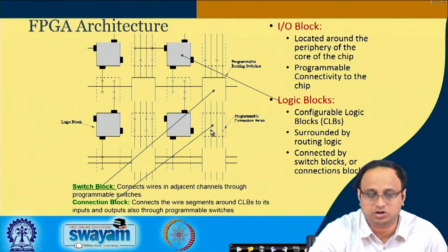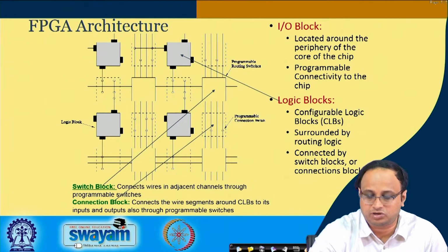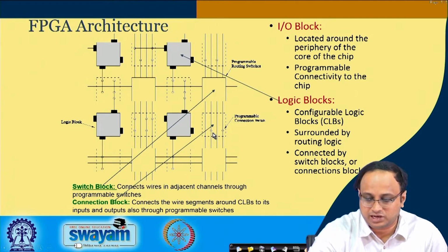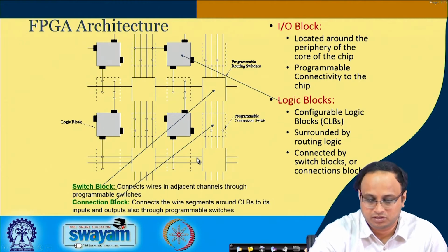For example, if I want to turn on a switch, I need to program 1 over there. If I want to turn off that switch, I will program it by 0. So it's basically using digital switches, to be more precise. At the end of the day, you have a design, and your tool will give you a 0-1 pattern, which is often called the bit file, and you take that bit file, and the bit file configures these switches. And therefore the FPGA gets reconfigured, and not only the switches but also your lookup table, and your entire structure gets reconfigured to work as you intend.